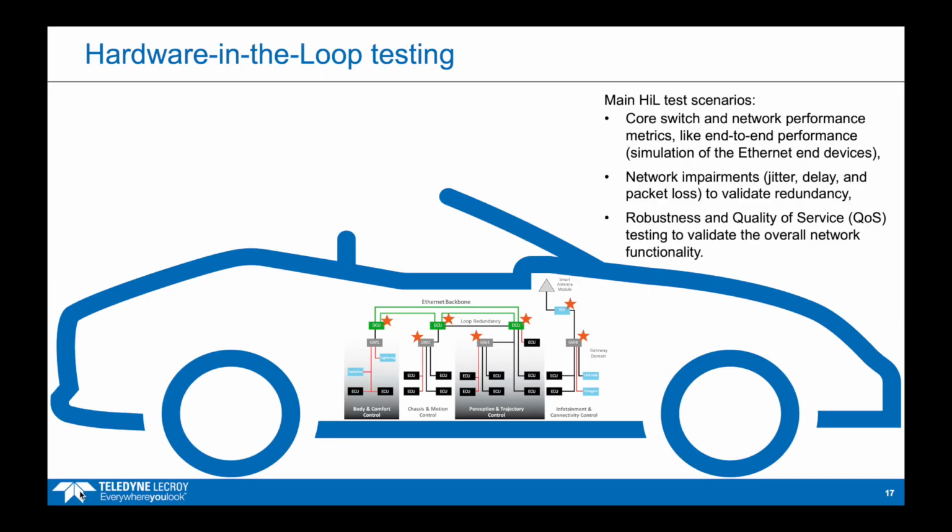The following stage is known as hardware-in-the-loop, or HIL testing, and this is where we go from testing components to testing the whole system. This is where the single device is integrated into the physically available or partially simulated full system, like the Ethernet backbone, the ADAS domain, infotainment domain, or even the whole vehicle's electronics. The related automotive development stage can be described as sample C/D, fully functional hardware and software, or production grade. The main purpose of HIL testing is to validate the system functionality.